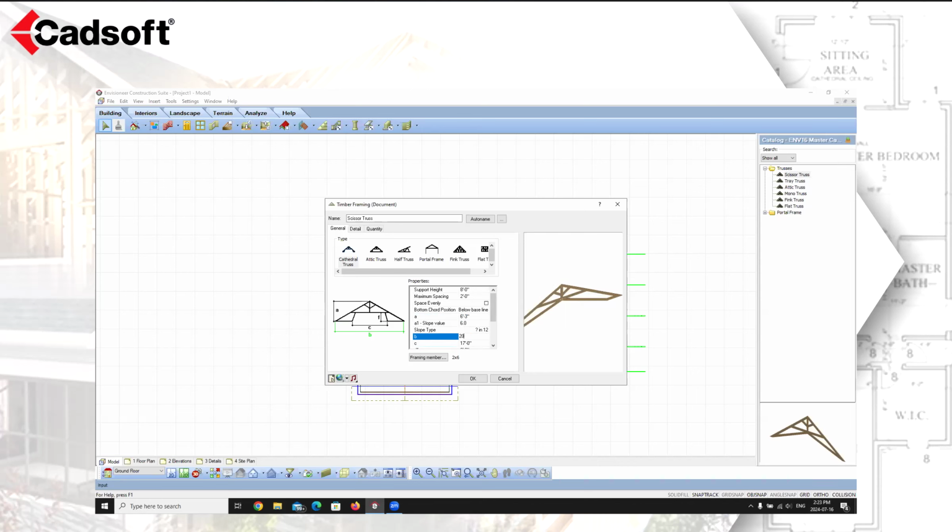So again, you can play around with these values, fine-tuning exactly how you want things to be laid out. We can say I want that to be 15 feet, and that's just going to help with the bottom chord of where we want the piece to be for our design. Here, again, D1 is going to control any kind of webbing material that we want in here.